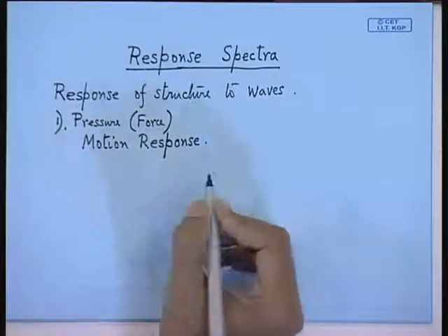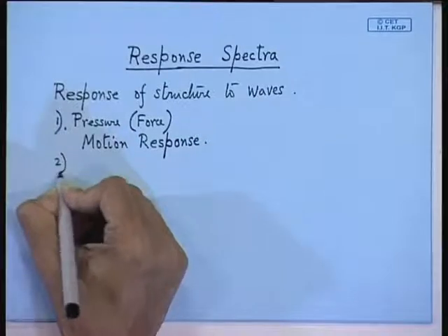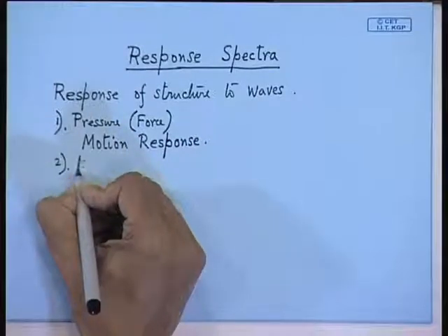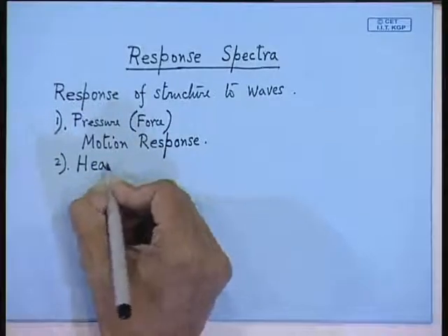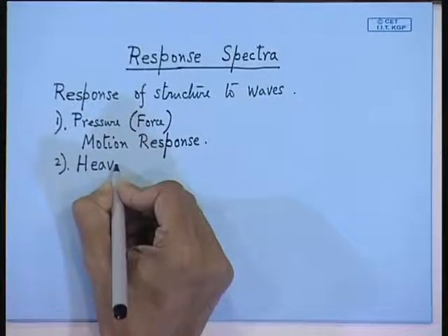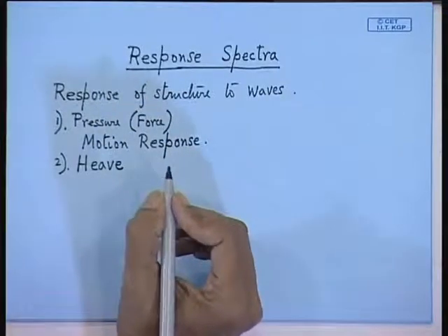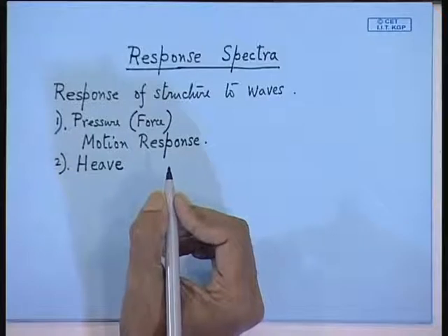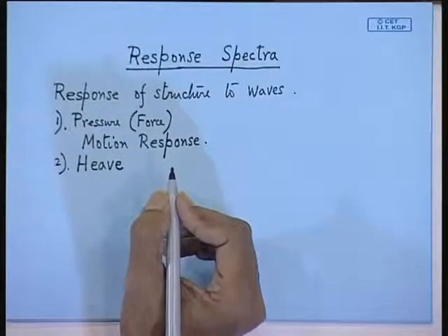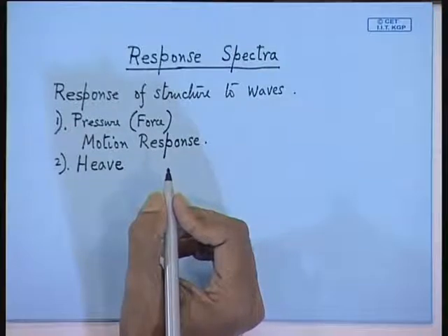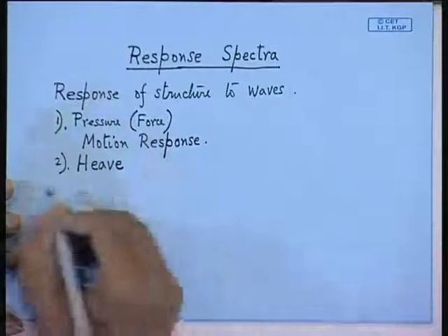Now what is the motion response? We are interested mainly in heave. Heave, as I told you in your offshore engineering class, is a very important response of offshore structures, because if you get too much heave, you have to stop drilling or taking oil from the well, because that will snap your marine riser.